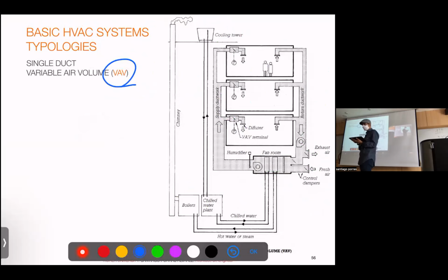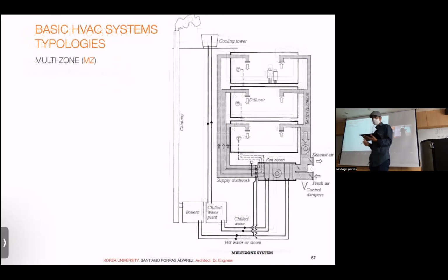Which is basically the same system, but you have a damper in each floor. So you cannot change the temperature, but you can change how much air you get inside. That's okay, because you can regulate what you have. It's more expensive if you have a lot of control elements and electronics there, but much more efficient. The problem is if you depend on this air, on your ventilation, the air you breathe, you can never totally lock, right? So this is a limitation of mixing two systems in one, just the air you need for breathing and the heating, cooling, but still better quality.